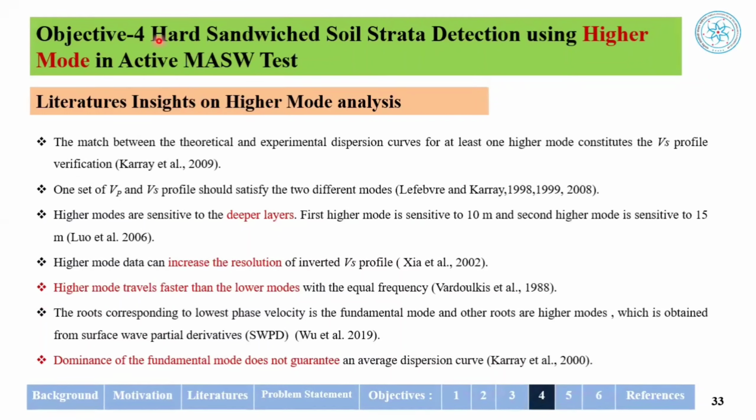The fourth objective is related to the hard sandwich soil layer, using the higher mode analysis. There are various literatures available on the higher mode. Higher modes basically have phase velocity with a higher magnitude as compared to the fundamental modes.